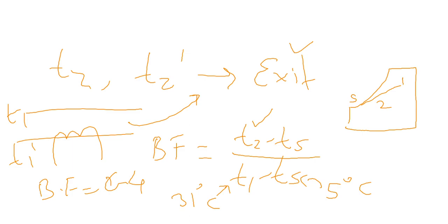I'll just once again repeat what we had done as a methodology, and then we'll stop this video. What was given was a cooling coil whose capacity was 4 TR. Your initial state was known, T1 and T1 dash were known, and you wanted to find T2. How did you find that?